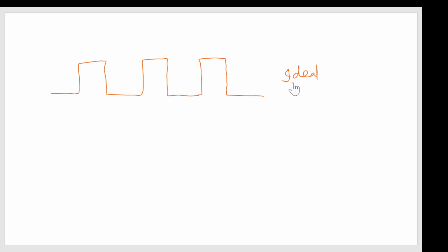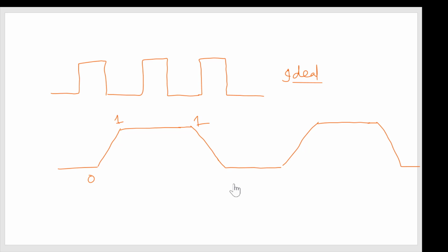So before we start the timing consideration, we'll first give a clarification. Whatever you have seen as your digital signal till now are in proper square shape or proper rectangular shape depending on the duty cycle. But in real time circuits this is only an ideal waveform. In real time you are going to have a clock something like this. If you look at your Wakerly book, you are going to see all the clock signals something like this. So what it means, your clock will not go from 0 to 1 all of a sudden, or 1 to 0 all of a sudden. It takes some time to move from 1 to 0 or 0 to 1.